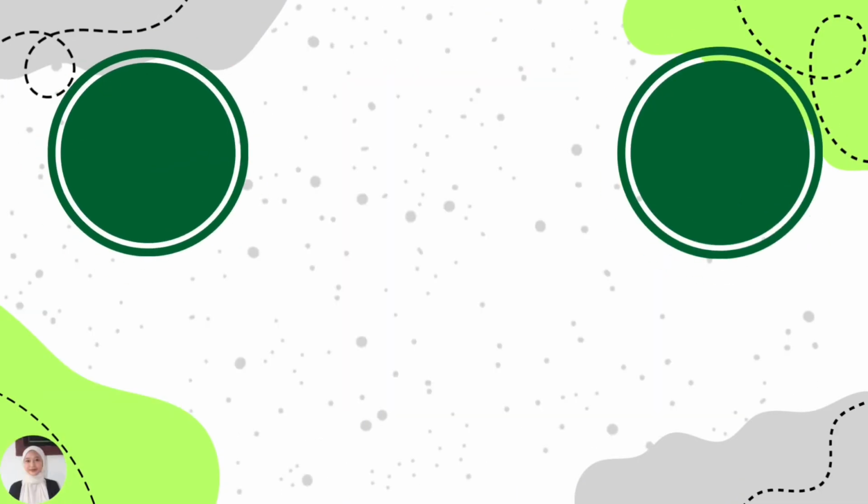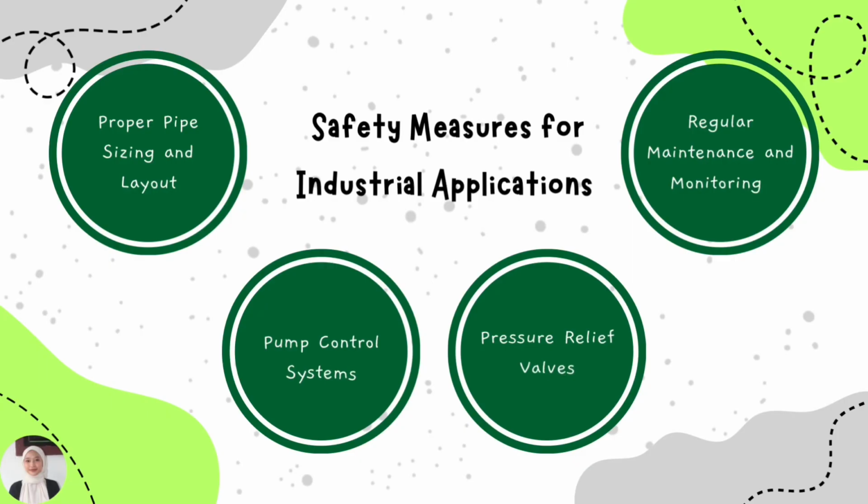Okay, next is safety measures for industrial application. So the first question is, in the context of industrial application, how will the proposed safety measures address potential issues like water hammer and pipe burst? The first one is proper pipe sizing and layout, because ensuring the pipes are correctly sized and laid out with adequate support minimizes the chance of pressure fluctuation.